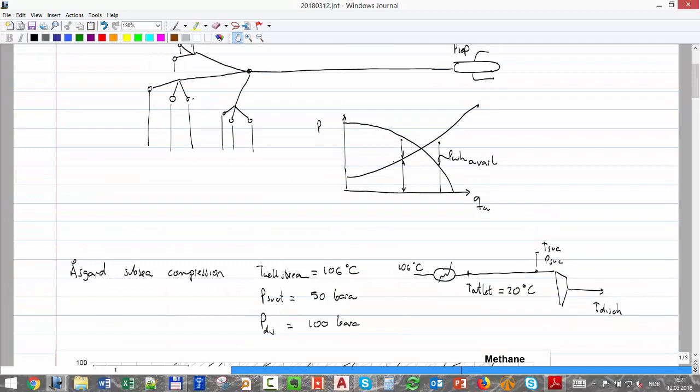To visualize: for a choke, you say I need a choke to give me this delta P for that rate, and almost always I will be able to find a choke that provides that. I have to care for some things, like critical flow and erosion, but I almost always will be able to find a choke.